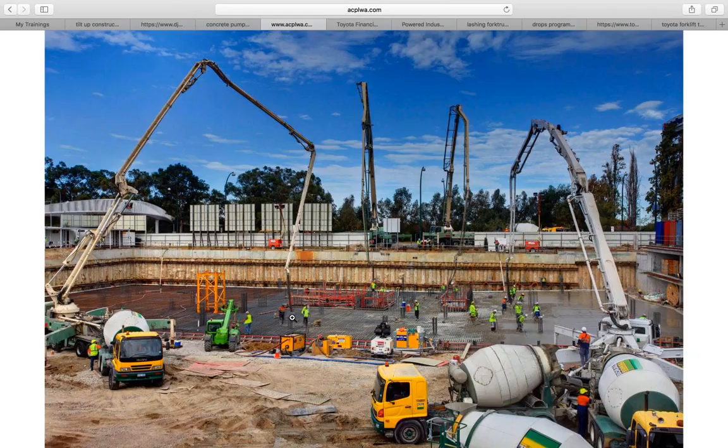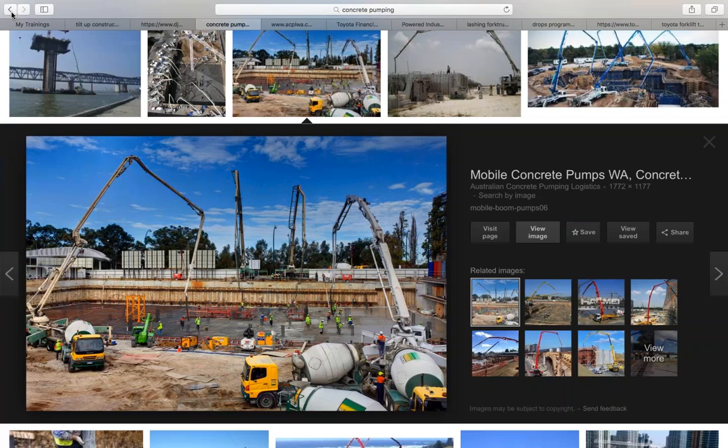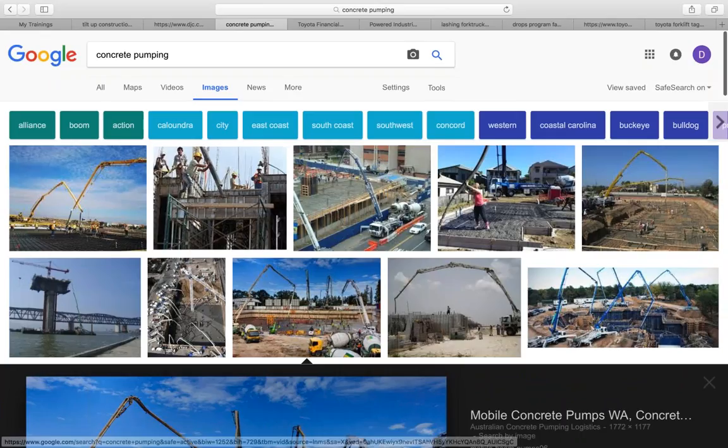using approved respirators. Like we said, if we're using approved respirators, we had to have gone through our medical evaluation. We've had to have gone through our pulmonary test and ultimately been fit tested within the last year. Okay. Also using wet methods for cutting, chipping, and concrete. What are we talking about? Basically wet saws. So let me go to it. And it's considered an engineering control, and it could possibly be an administrative control too.